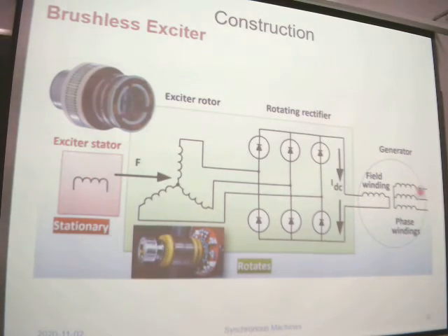This is the synchronous generator. This is the stator, the three-phase stator windings, connected to the AC source, to the grid. This is the DC field winding.